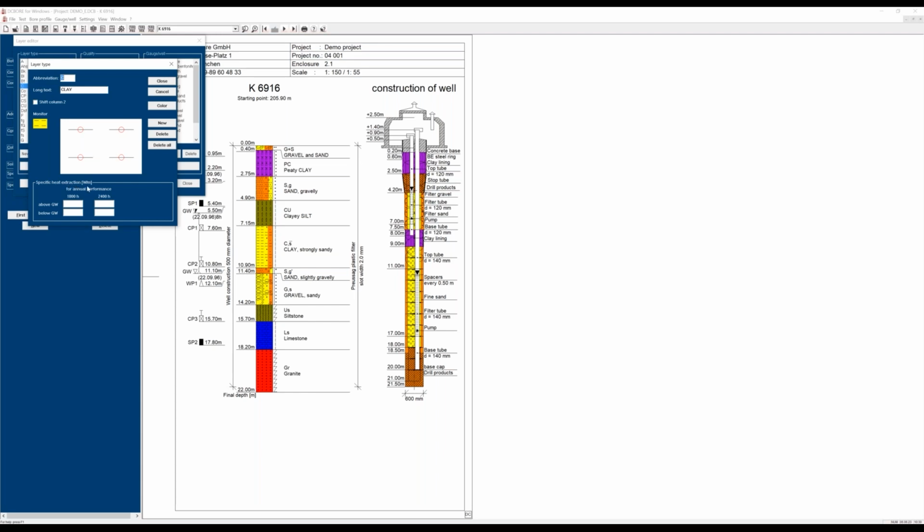So for example, how many watt per meter depth can be taken from the ground for heat extraction. This is different for certain annual performance of 1,800 hours or 2,400 hours per year, and is distinguished between above groundwater and below groundwater.